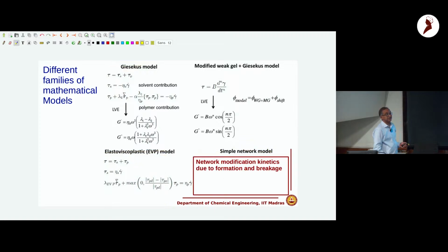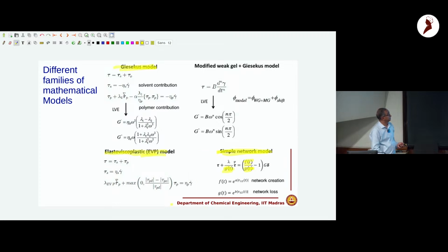One question. The G prime, G double prime we got from, let's say, LAOS measurement, and these are the first harmonics only. Right. And from the linear viscoelastic model also, that is the similar parameter you are getting in the large strain only. No, so a linear viscoelastic model by definition will show G prime, G double prime constant, because by definition it only has one contribution. See, this contribution is presumably reducing because there are other phenomena which are happening, and we are not accounting for those in a linear viscoelastic model.